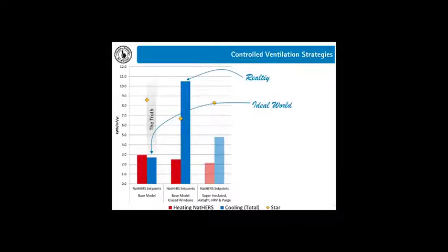So what we've got is a scenario in the NatHERS system, or the assumptions in the NatHERS system, that's just assuming this ideal world, these ideal occupants, 10-star occupants that are operating their buildings. In reality, we may have the second case and the cooling load driving up massively. The truth probably lies somewhere between them, but in the third case, we can actually control that and actually deliver outcomes because we're using controlled systems to do it.